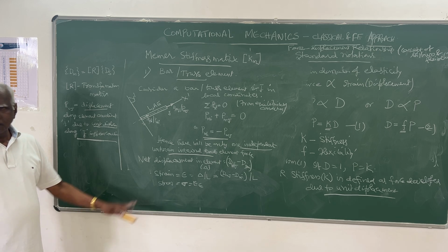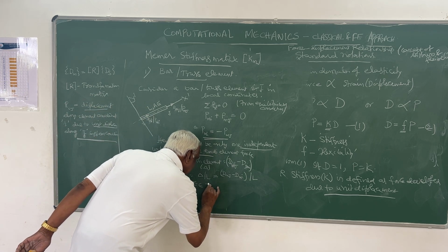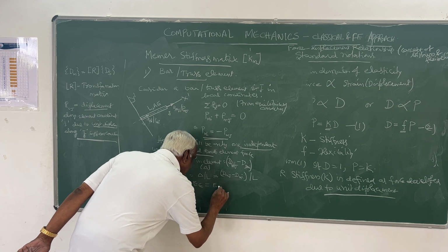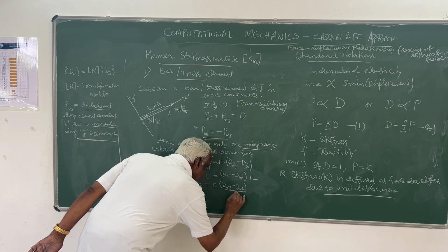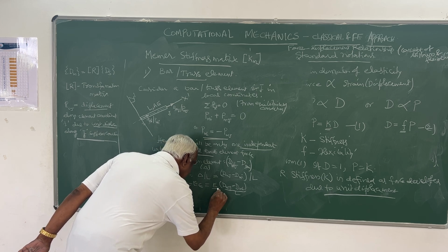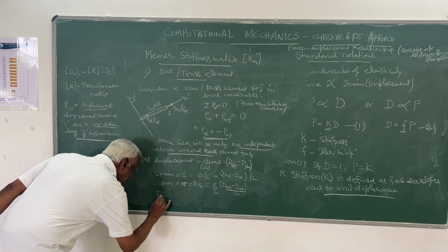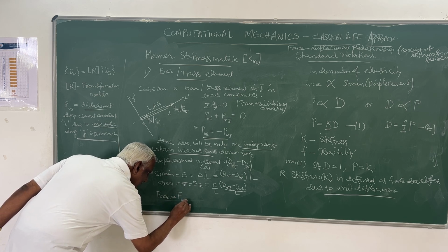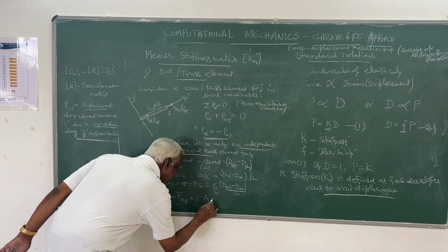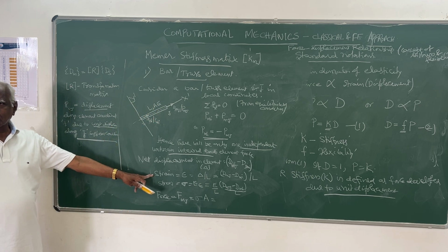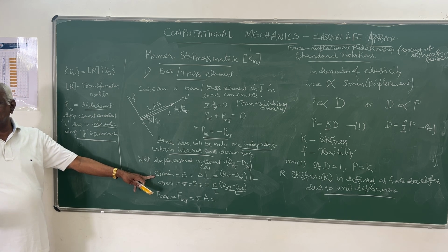It is within the elastic domain: stress is proportional to strain, with a constant of proportionality that is the modulus of elasticity E. Strain is the net displacement divided by the original length.